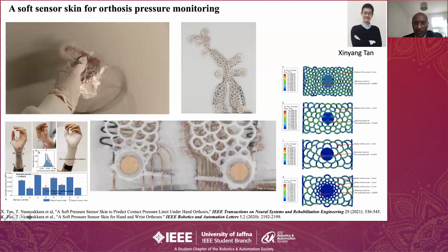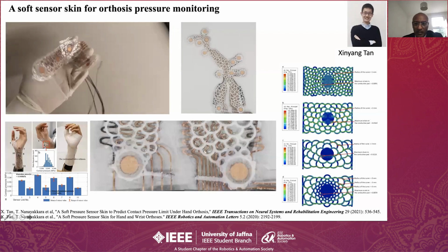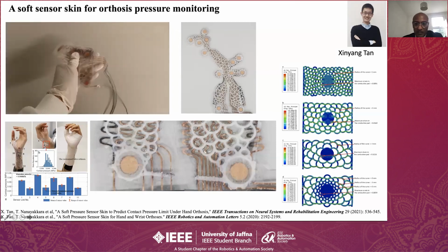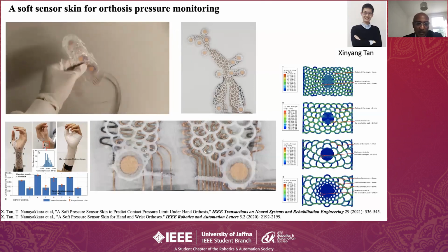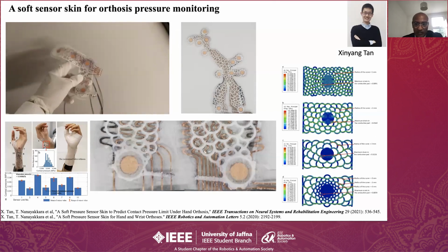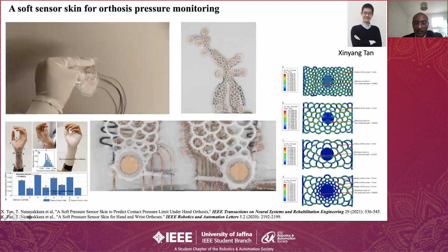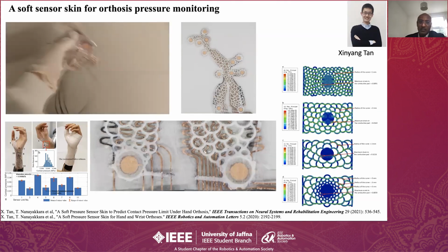The important point I want to make here is that with careful design, you can isolate the sensor from external disturbances. If you put a sensor underneath this orthosis device, due to various shear forces, like the hand moving around and the skin growing and things like that, those pressures will also be captured if you just leave the sensor. So we wanted to isolate the sensor from that kind of external disturbances.